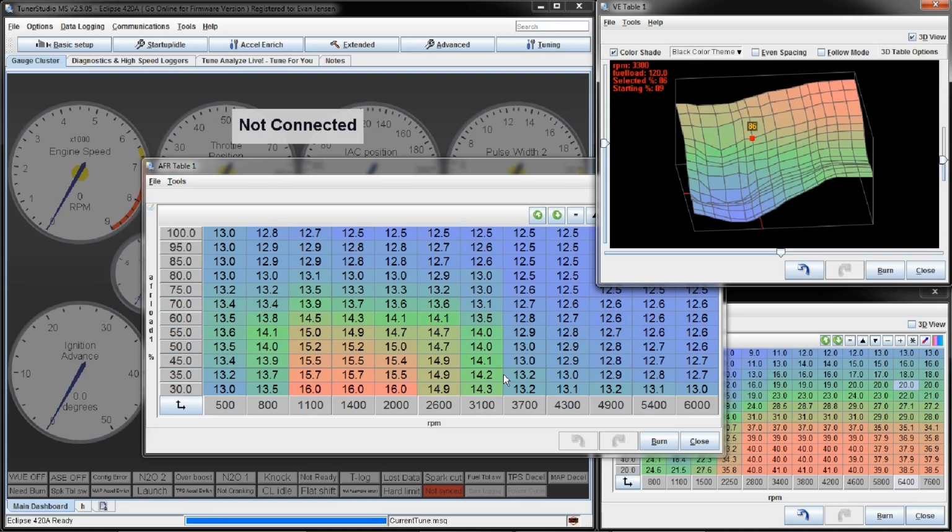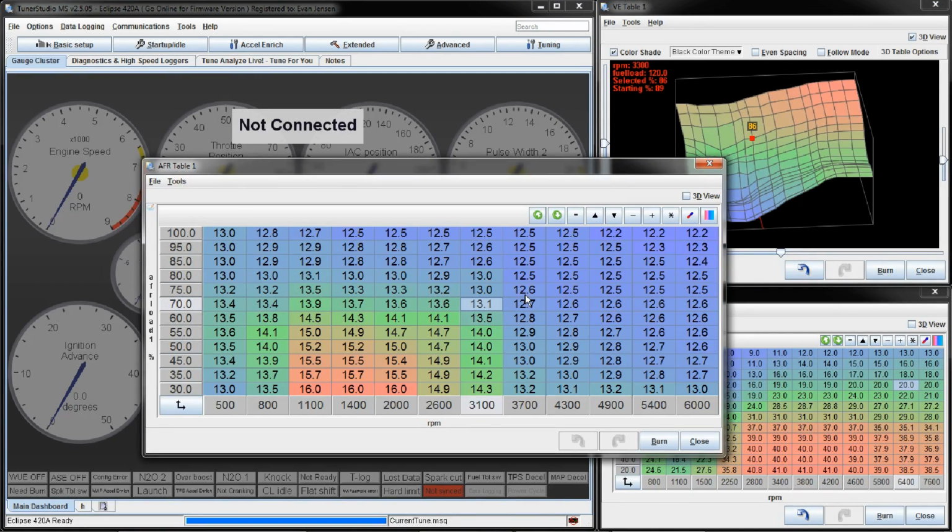It's going to trim this fueling to match this AFR. And the auto-tune does a good job at trying to take out all the transient stuff, anytime things are changing really quickly. So if you are doing auto tune, make sure that you try to keep your car in nice steady states and things like that, so that way it's got a chance to correct.